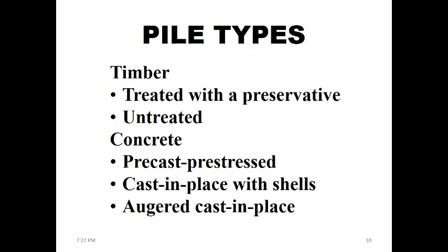For concrete, it can be precast, prestressed, it can be cast in place with shells, and it can be augered, cast in place. When it's precast, prestressed, it's obviously done off-site, then moved to the construction site by trucks. But for certain projects where the available roads do not allow these large structures to be moved to the construction site, it can be cast in place.